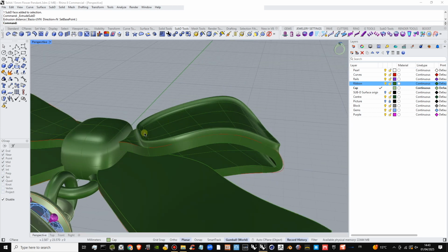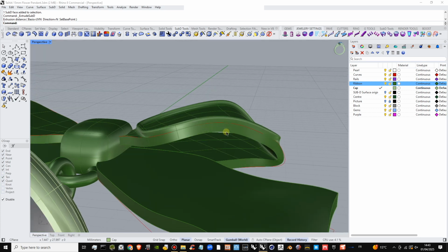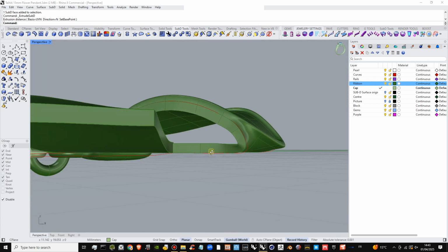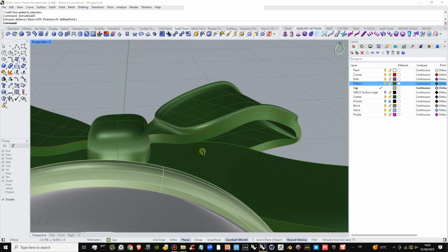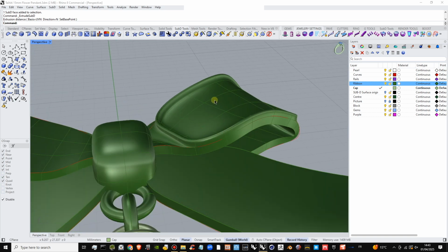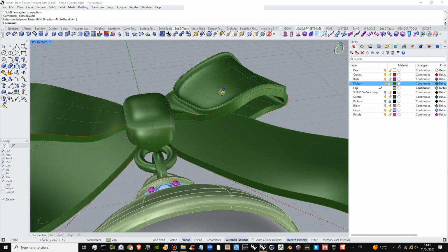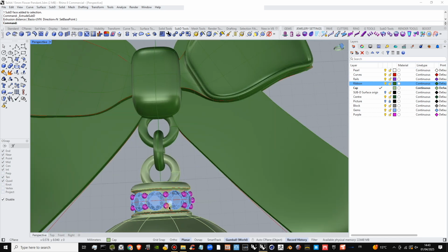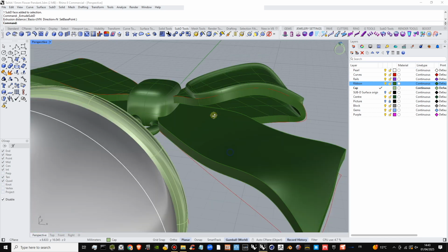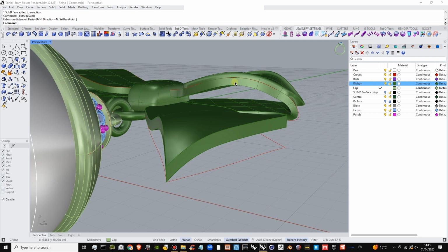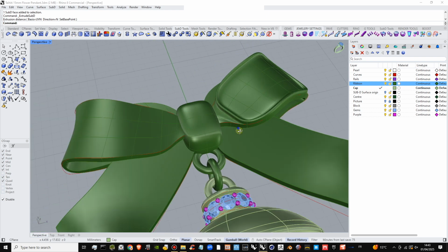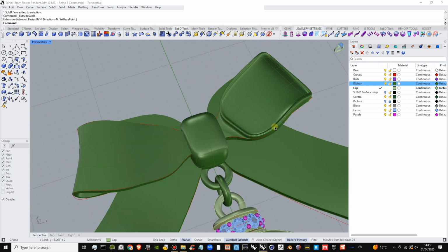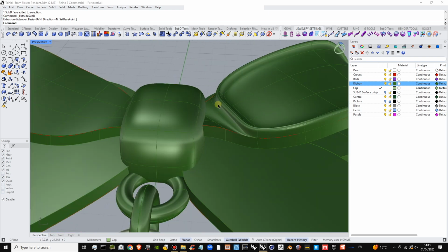Why do I build the ridge up? Well, because we've got a 0.7 millimeter or 0.6 millimeter material here, and you don't want to lower into that material like we did here with the cap. We would then have too little material left to set the stones in, and it could break through. So you just want to do a ridge. You want to lift the area.